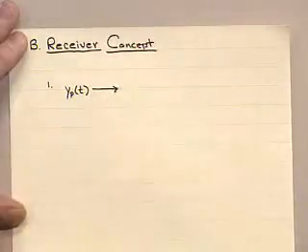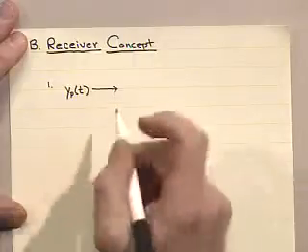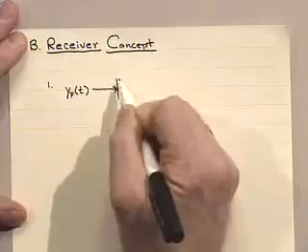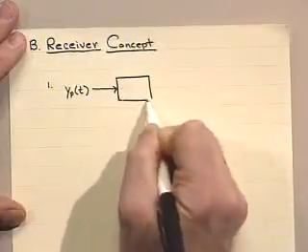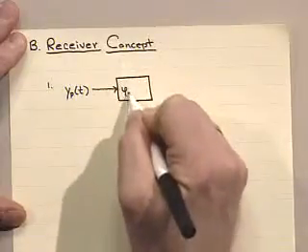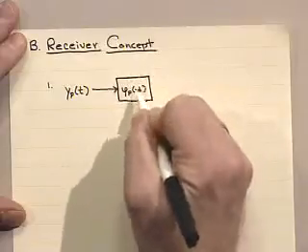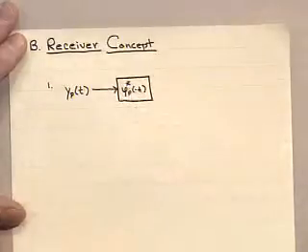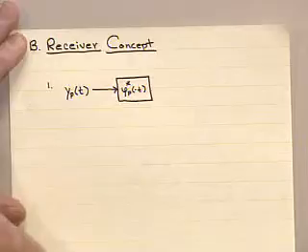So in this world of suboptimality, symbol by symbol detectors and equalizers, the first thing that we're going to postulate we could do in a receiver is to run through a basis function which is matched to the pulse response itself, and we're going to normalize the pulse response, so we can always normalize a function by dividing by its norm.